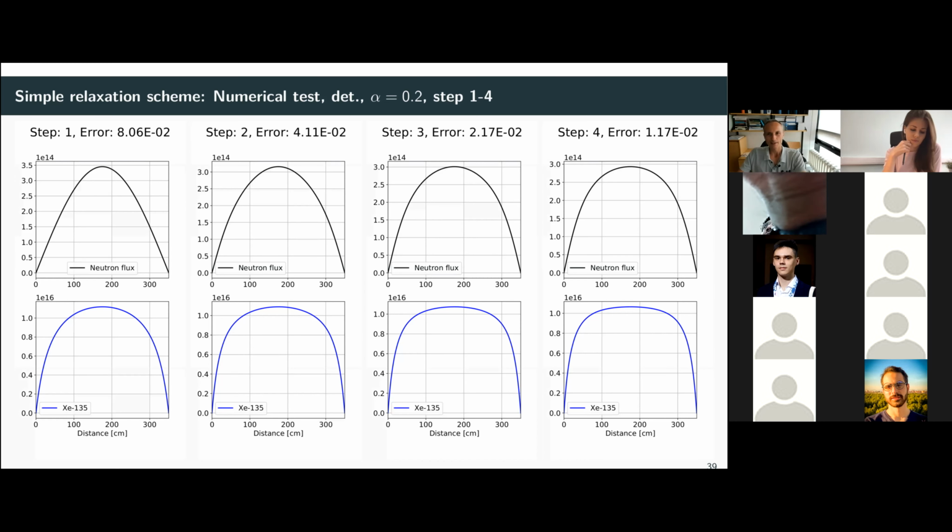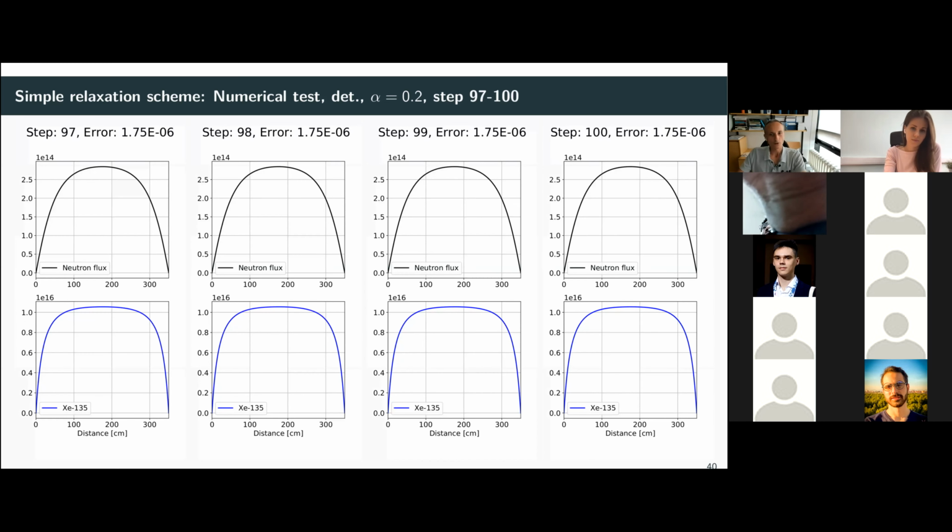Now it's probably not stable if I run many more steps, like if I run a couple of thousand steps, more than likely the left to right oscillation would develop. It will be damped down quite a lot because the step size is 0.2 only, but eventually it would happen as well. But you know, if you were using just the deterministic solver and you run 10 iterations, you will get very good result with this.